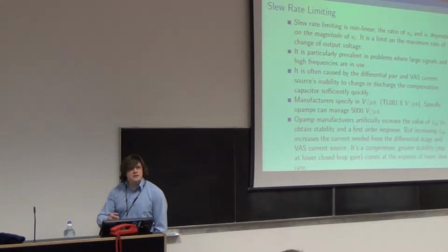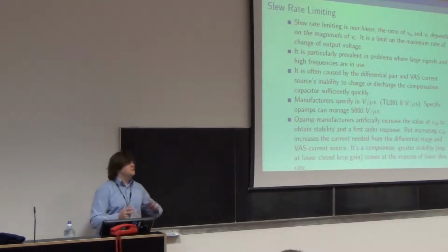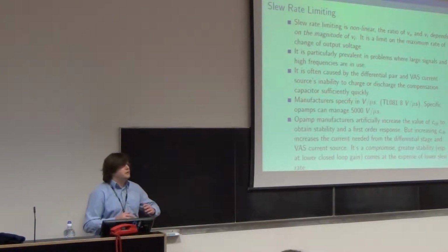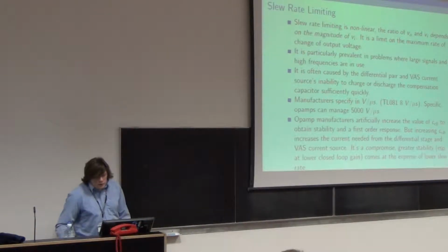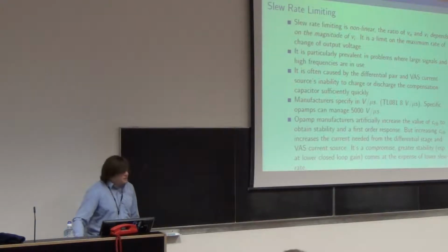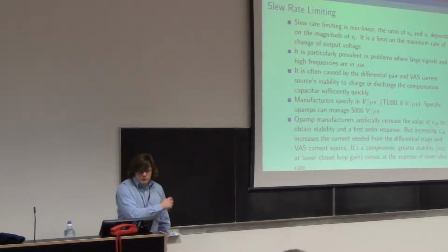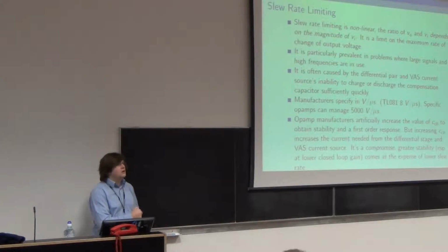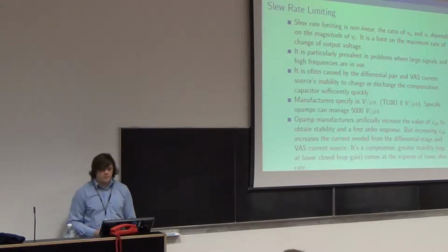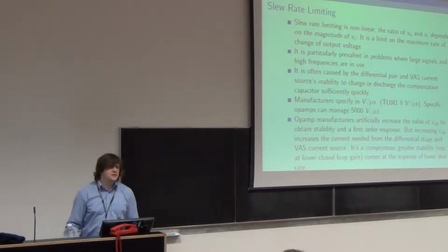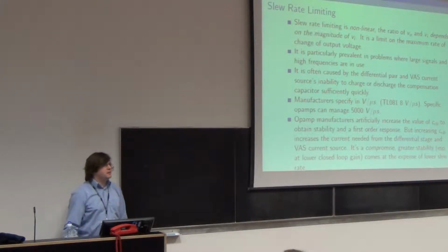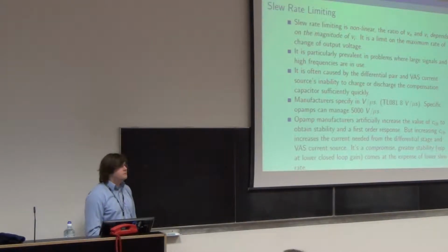So it's not like a linear system where you choose any frequency, any voltage, you get the same answer, just scaled. So the cause of this, we have to charge up that capacitor, which gives us the first order response, and it's the charging up of the compensation capacitor that we are worried about. That's a bit of a simplification, but pretty much true for almost all situations.